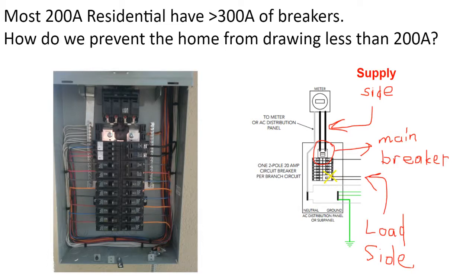Obviously, this is not the case for solar, and National Electric Code allows an exception. When the solar breaker is located at the opposite end of the bus bar from the main breaker, rather than inserted somewhere in the middle, so if the main breaker is at the top of the panel and then the load side solar breaker is located at the bottom of the panel, an additional 20% amperage allowance can supply the electric service panel.